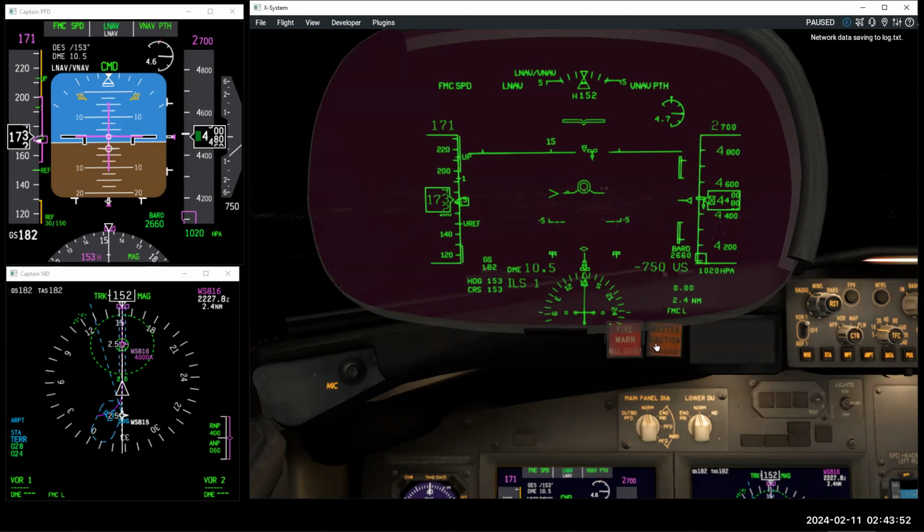And the next will be gear down, flaps 15, speed brakes armed, and open the window, set flaps 15 speed. And then once we start down, landing flap and VREF, in this case 30+5, and then set the missed approach altitude, which is 6,000 feet. So we'll cut it loose and we'll try to get all this done as we are in position. Now, if you notice,